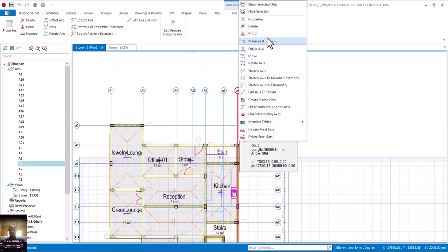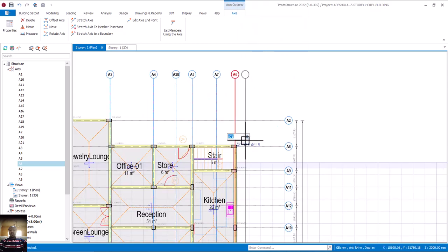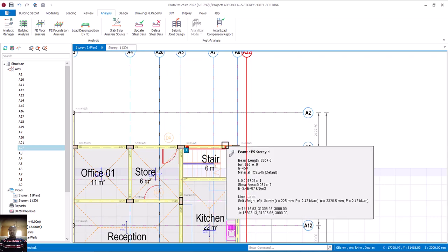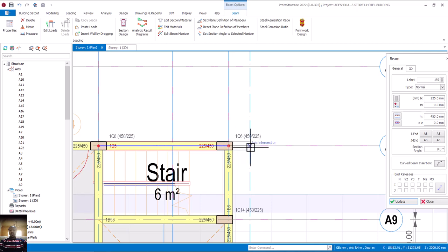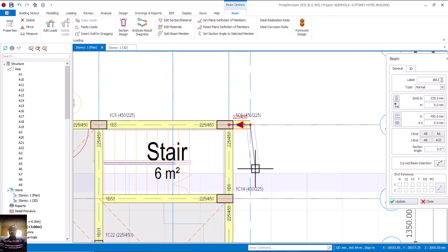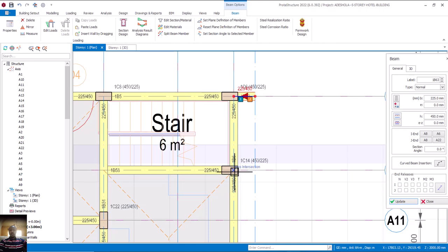Click on this, right click, and click on offset. From the offset, I'll press my F2. That's 600. Enter. Is that okay? That's fine. So from this point, I'll take my beam property. Though I know that this 450 beam depth might not be sufficient. We need something higher than this. The reason is because the column that is going to rest on this is going to carry about 4 floors. So you should expect a bigger beam depth in that place, I guess, from experience.